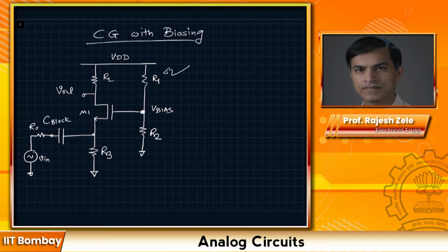In this case, how do you quickly figure out the voltage gain of this circuit? Just by inspection. So here is a trick I'm going to show you. Let's call this source node V dash. We know that the gain from V dash to V out is given by Gm times RL. We just did that analysis a few minutes ago. Now we need to figure out the transfer function from V in to V dash.